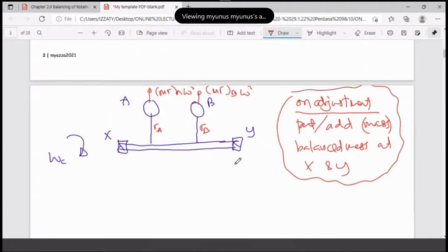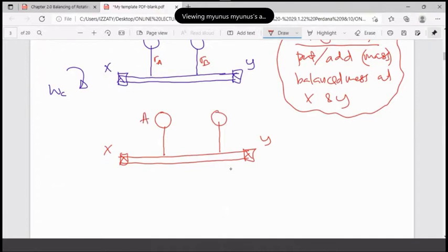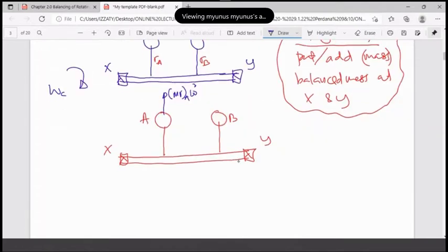So you are saying that okay, I'm going to do this one. There's no calculation here, just theory. This one is the same shaft, identical. This one is the bearing, of course, and this one is force. Again, same thing. Put A, put B. The creation of the unbalanced force here will be pointing outward. Let's put it here as m_A r_A omega square, and you have here the same thing, m_B r_B, also omega square.